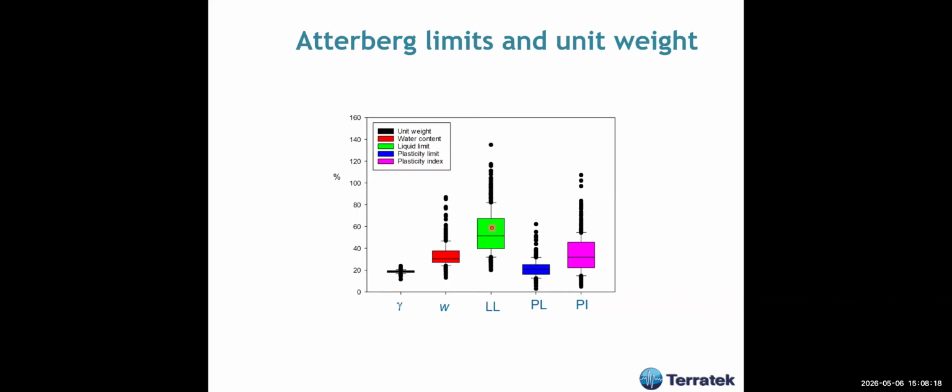Liquid limits are not that high, though some of the material presented high plasticity of 60. The plastic limit is about 20%, and the plasticity index of these clays varies from say 20 to 40%.